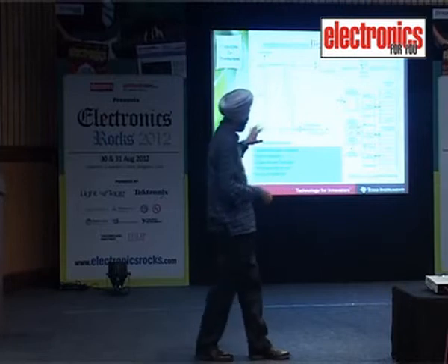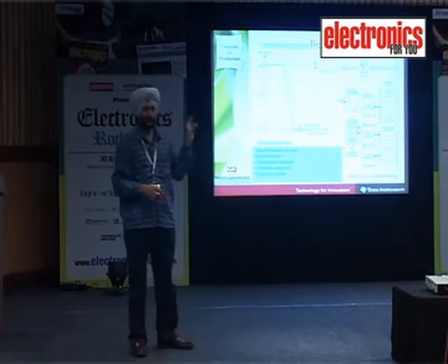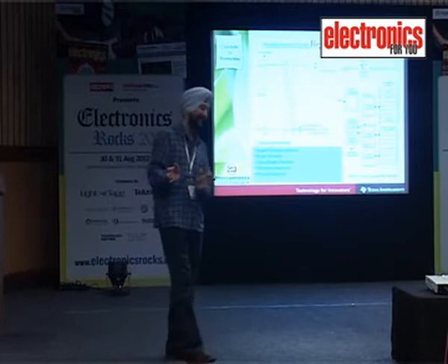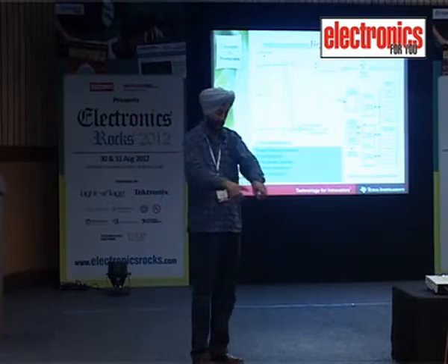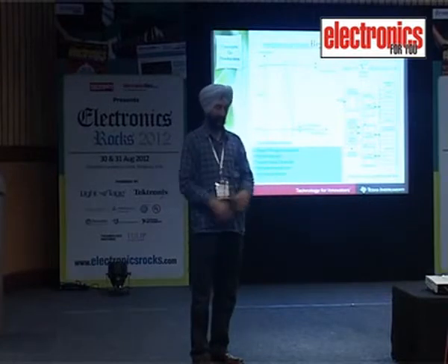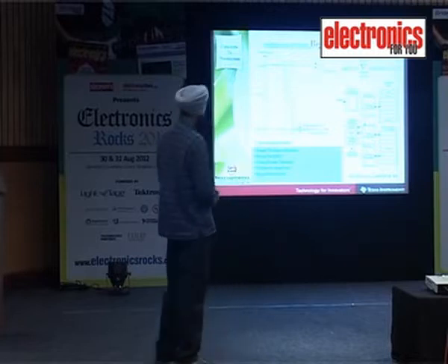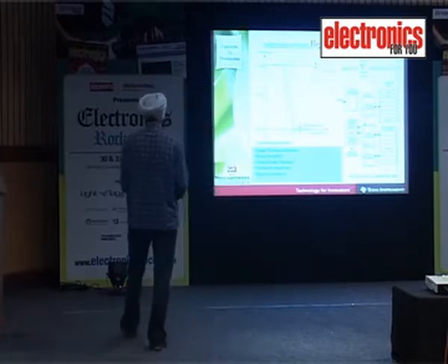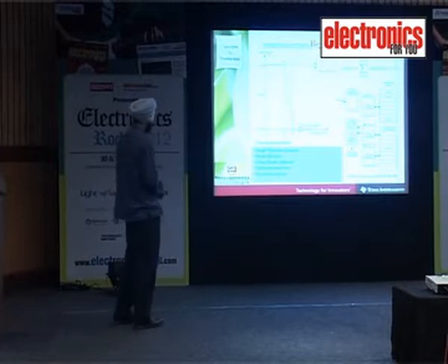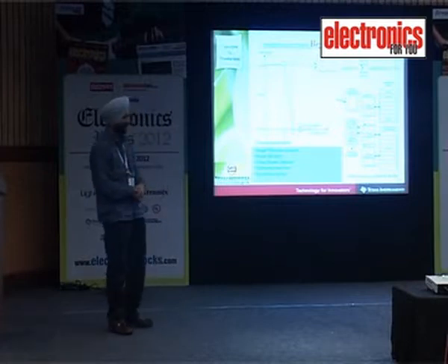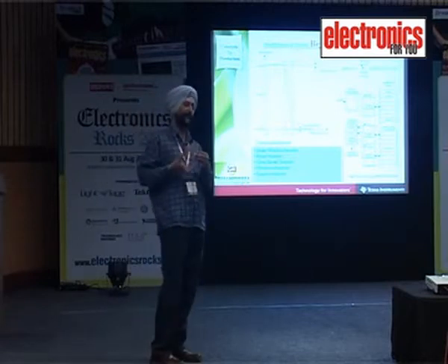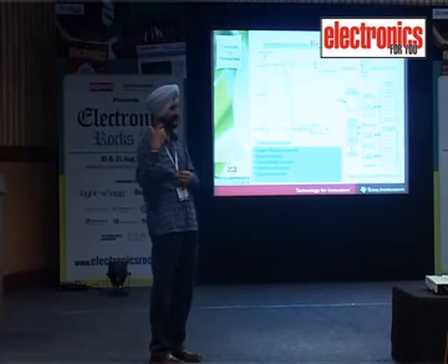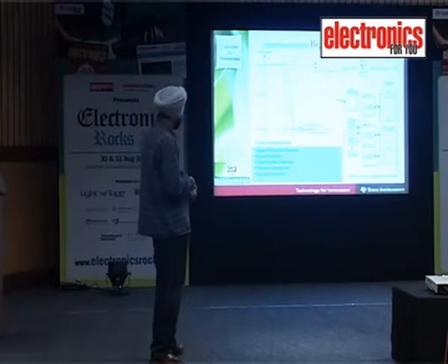Now, using some fine algorithms, you will be able to detect whether this glass break belongs to the framed window or whether it was maybe your nice dining table, right? Up to that depth, it will be possible with the help of this MSP430 based application. Vibration analyzer: you can find an industrial application sometimes in bearings, where if there is a fault in the bearing, we normally detect it by listening to the sound or to the vibrations.